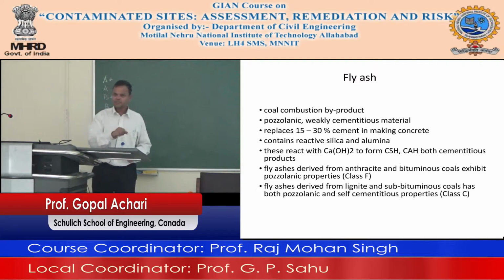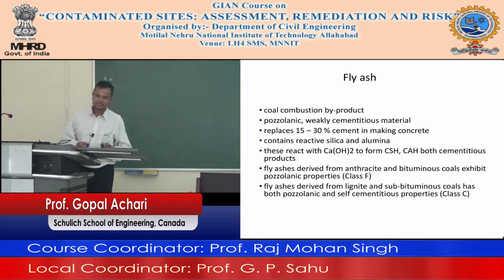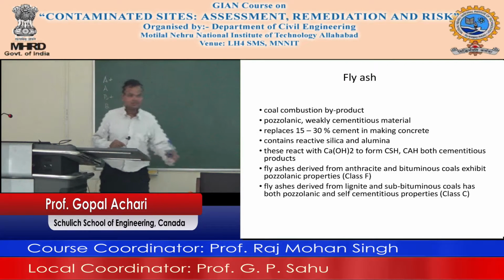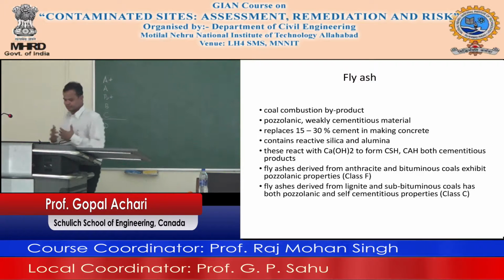So you add cement to fly ash. The fly ash can utilize the calcium hydroxide that is produced in the hydration of the cement to form cementitious material, right? So it will actually be beneficial. You see the symbiosis here, the benefits.